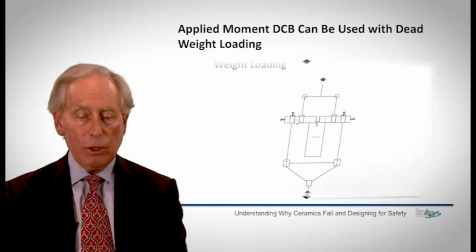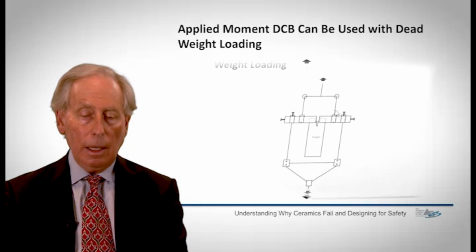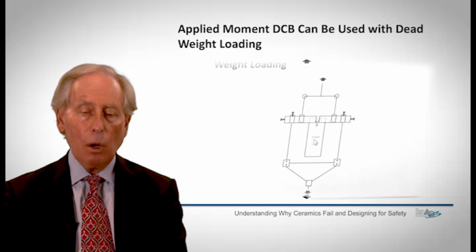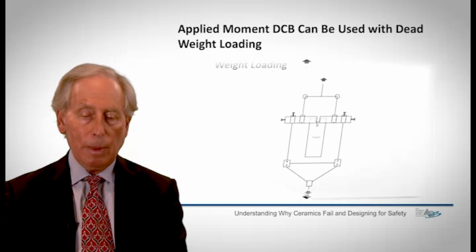You can see here how typically we would have loaded this little trapeze arrangement, in which now you can put this in a test machine and you pull in this direction, and in this way if you rest the specimen on some arms up here, you're actually applying the moment and the crack grows down the specimen.